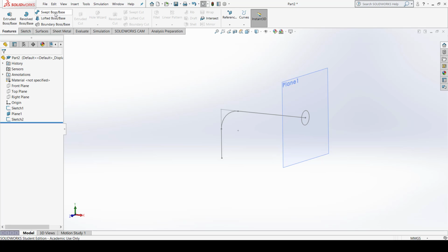You also make sure that this command is only applicable to a single sketch element only. If it is a circle, then the profile will be created like a circular pipe structure. If it is a hexagon, then the pipe will be created in a hexagonal structure. So it is created only for a single profile with a constant characteristic. Let us say the diameter of this circle is constant now.